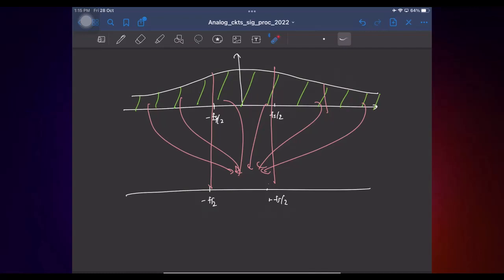Does it make sense? My confusion was that if we consider a general signal, when aliasing is happening, in a given frequency band it need not alias in a constructive way. We can't always add up the power. Here we are doing it. Power spectral density is basically mod of something squared, so it can never be negative. Power spectral density is always positive, so you'll never have a destructive case here.